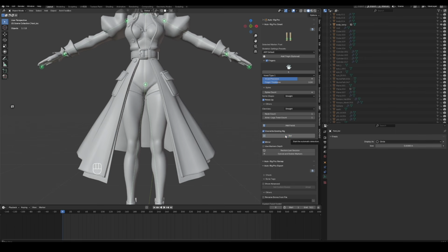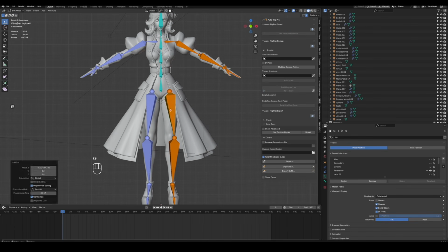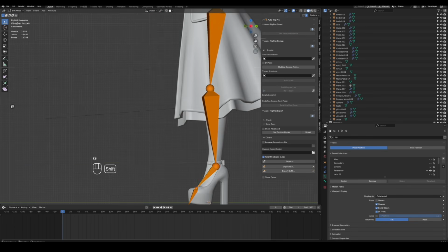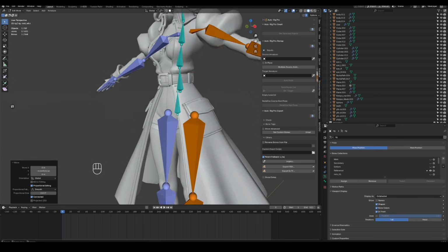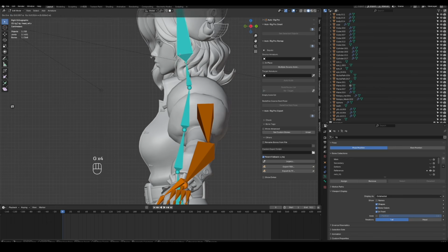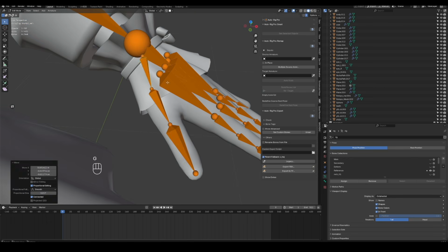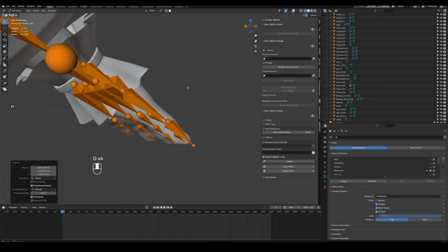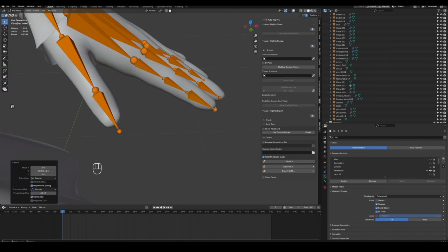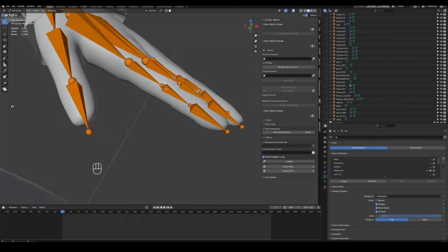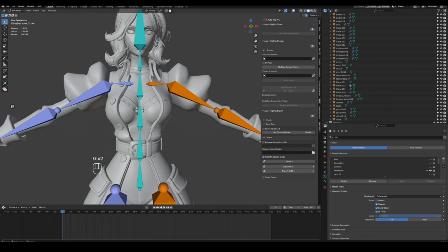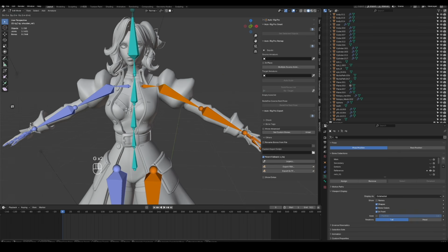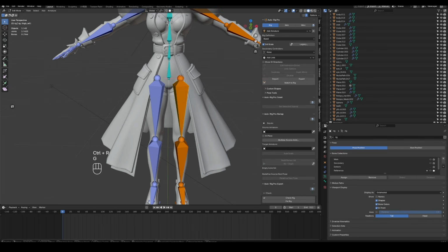Next click Go to generate the rig. Once it's generated, don't rush. Tweak the joint positions to match your character's proportions. In the side view, place the backward bones as close as possible to the body's center of mass. Then adjust the finger rotation directions to match your model. When it looks right, click Match to Rig to generate the controllers.